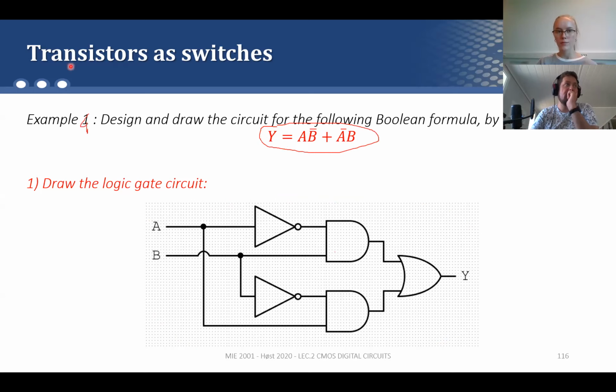So at this point, I have A inverted, because A is the input to the NOT and then it is inverted. In the other input, we have B, and then the output of the AND is A inverted B. On the bottom side, we have B inverted and we have A. The output of the AND here is A, B inverted. The OR does the sum, right? So the result is A inverted B plus A, B inverted. It's like an XOR or something like that.